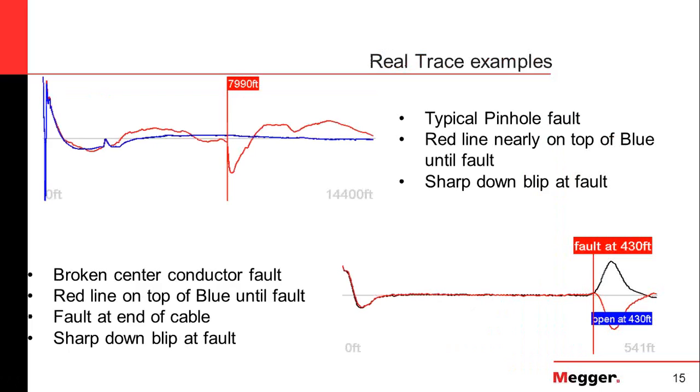So there's a study out there that shows high voltage impulses can be damaging to a cable. Now, if you actually read that study, they were talking about lightning bolt pulses from lightning strikes. And they also took one of the largest thumpers made at a very high voltage setting and showed that there is a possibility of impulse damage to a cable that's already heavily aged.